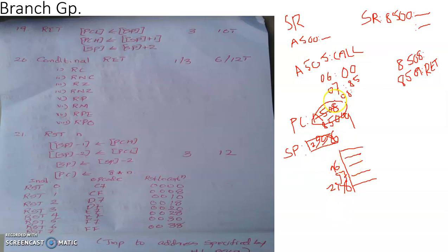To this location we have already saved the least significant 8 bits of the address, 08. And the content of the memory location whose address is the stack pointer content plus 1, that happens to be 2997, which contains the most significant 8 bits of the address that was pushed into the stack memory location, will be taken back to the most significant 8 bits of the program counter.